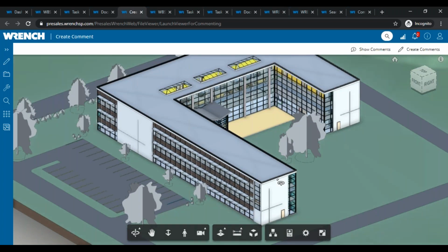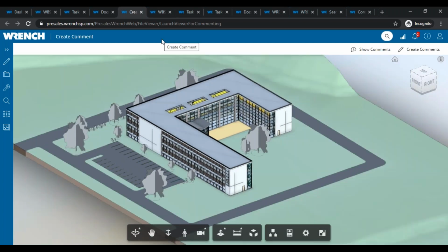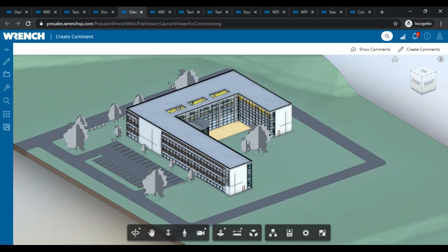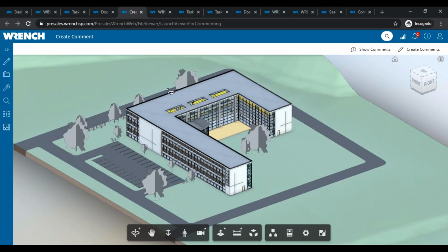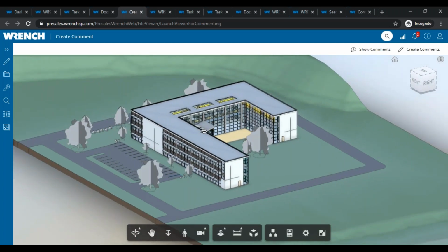So now once the comments on this particular model have been taken care of, and all these are completed, then this model is frozen, and this model can even be shared with your contractor in case your contractor is using this information to produce your shop drawings and other detailed design drawings from you. So the first part of our data that we are exchanging in the common data environment is the BIM model and the 3D models with all the related information between the various parties which are associated with this.